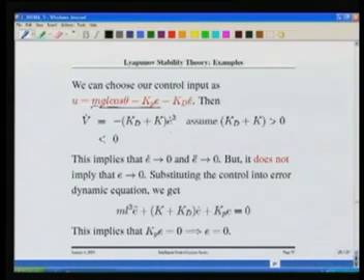Hope you are very clear about this. And obviously, why? Because initially k may be positive or negative. Now, k d plus k, because k d is my extra parameter I provided, even if k may be a very small quantity, the k d E dot term was actually introduced to make this quantity reasonably large, and now this is a positive quantity, E dot square is a positive quantity. So, V dot becomes negative definite.